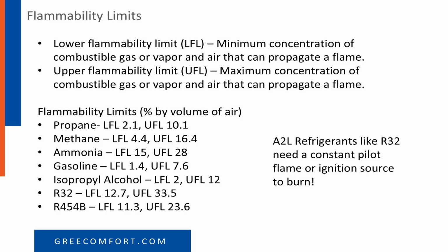propagate a flame. And when we also look at these refrigerants, when they have to burn, and Greg did a great video kind of showing this, and we can show it here at the end of the slides. A2L refrigerants, they need a constant pilot flame or ignition source to burn. So if you spray the refrigerant directly on a flame, it'll burn. You pull the flame away, it stops burning. So it's got to have that constant pilot flame. So again, A2L refrigerants are very, very safe when handled properly.